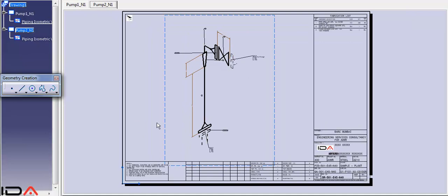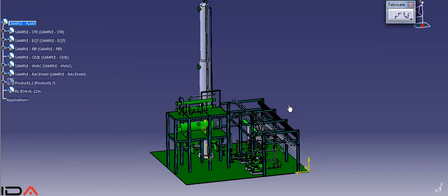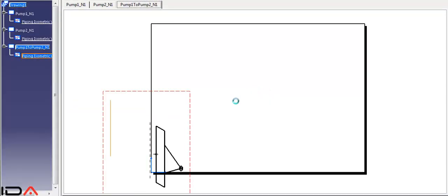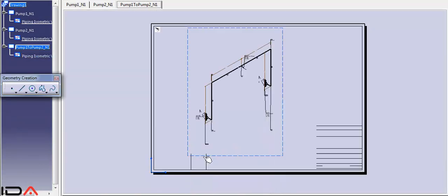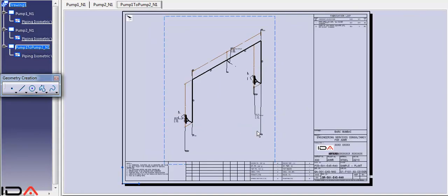naming the sheets as spool numbers, and all the details which are generated automatically. So here you will see, the next spool information coming in the drawing, and also the end styles of the symbol, the tagging of the component, all are coming automatically.